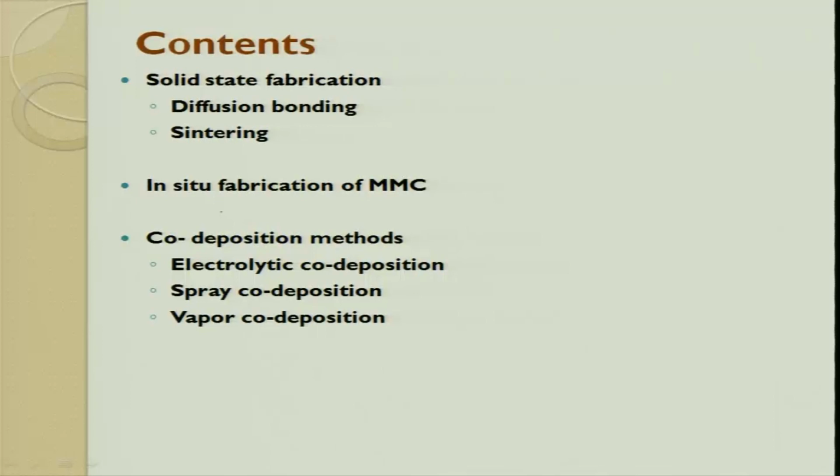Today we will see solid state fabrication, and we will also see in situ fabrication of MMC. That means when we add two ingredients, they react on their own and make both of them distinct, and it evolves. The other way is the co-deposition method. We would like to talk about electrolytic co-deposition, spray co-deposition, and vapor co-deposition. This is what we will try to cover in this lecture.